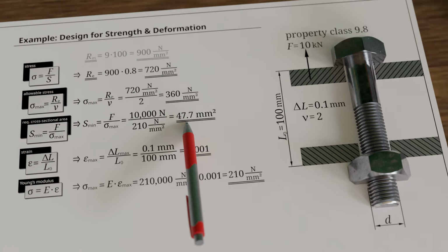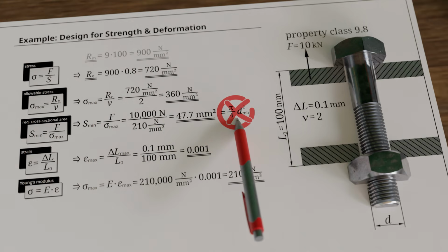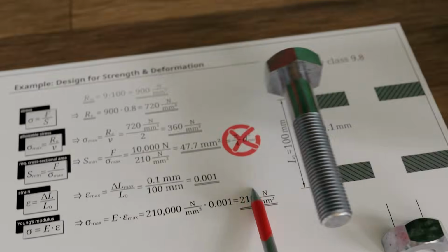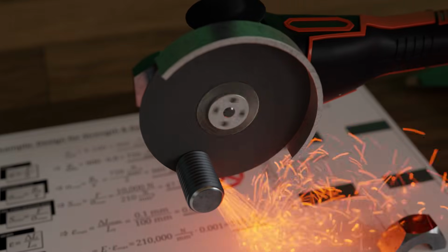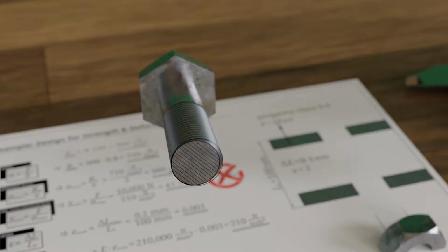However, caution is advised when determining the appropriate bolt size. One must not now determine the bolt diameter using the just calculated cross-sectional area and the formula for a circular area, as in the example of the previously considered bar. The critical factor for a bolt is not the diameter of the bolt shank, but the load-bearing area in the cross-section of the thread. To examine this, let us consider the bolt in cross-section if we cut it through at the level of the thread.